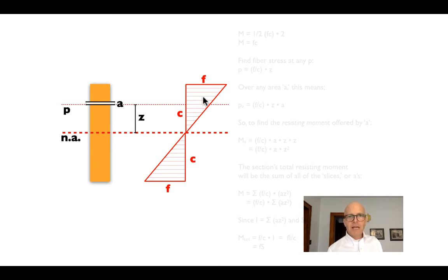The further we get from the neutral axis, the greater the stress is going to be in each one of those fibers or infinitely small little bits of material. And so if we can put all of the material at the extreme edges, right, to resist what's usually the compression stress across the top, what's usually tensile stress across the bottom, taking all of those little tiny infinitesimal areas and concentrating them at the beam edges, the beam is going to be more efficient.